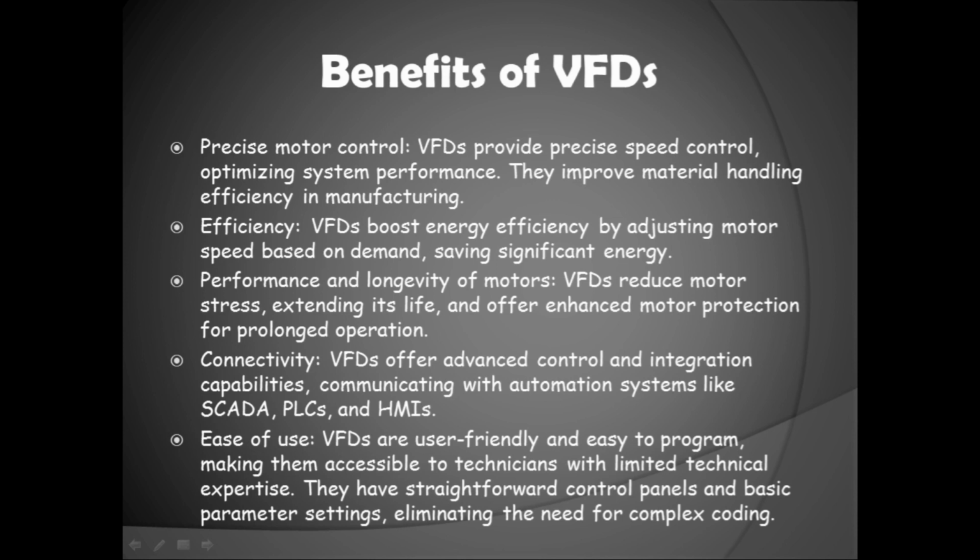Efficiency. Another notable benefit of VFDs is their energy efficiency. VFDs optimize energy usage by adjusting the motor speed in response to demand. While lower speeds might be sufficient in many applications, motors often run at maximum speeds, wasting energy. By lowering motor speed when less power is needed, VFDs minimize this inefficiency and result in significant energy savings. For instance, in HVAC systems, VFDs can adjust the speed of fans and pumps according to the cooling or heating needs, significantly reducing energy consumption and operating costs.